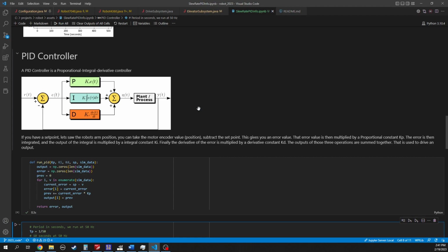And you can change that. If you look at the drive subsystem, I have it set so that when we get the position from the encoders, we're actually getting distance in meters. And we can do the same thing with the robot arm. We can get the rotation in rotations or radians or degrees or whatever you want. But anyways, let's say our arms are sitting on the ground. If you saw that video that we posted a couple days ago on Gilded, that's Fargo's robot arms moving to roughly horizontal and then using a PID controller to keep it there.